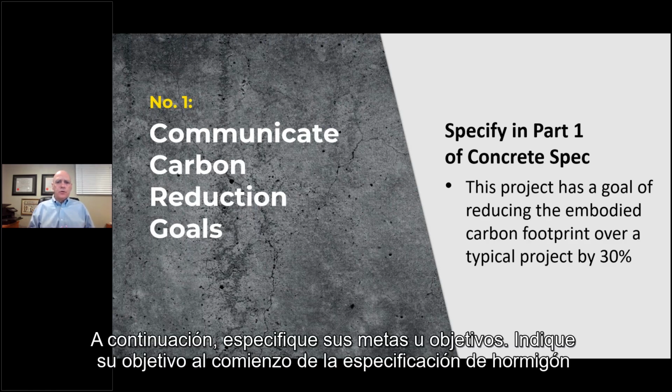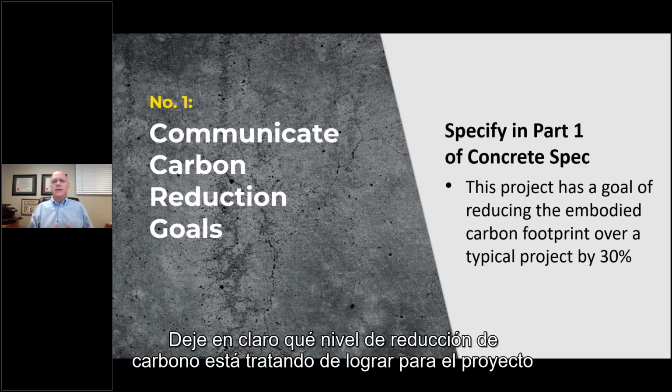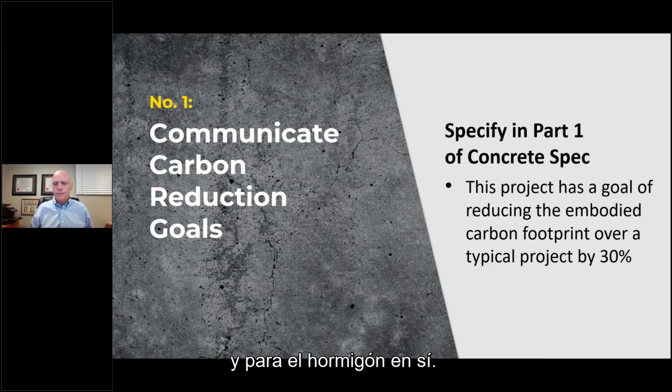Next, specify your goals or targets. State your goal at the beginning of the concrete specification in section 03300 of the specification, part 1. Make it clear what level of carbon reduction you are trying to accomplish for the project and for the concrete itself.